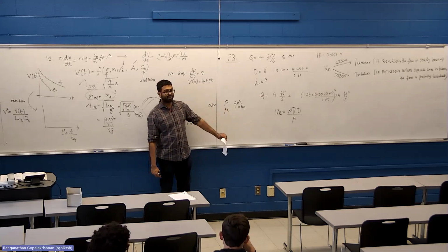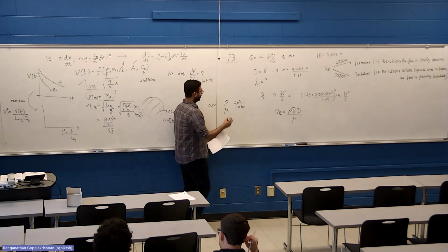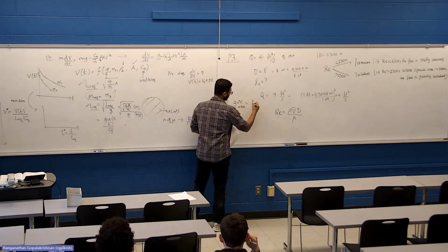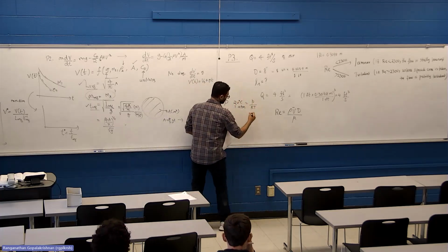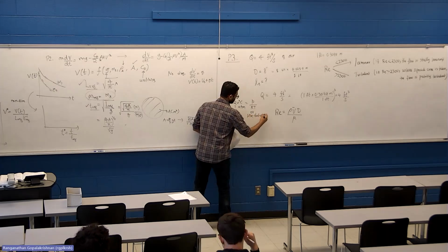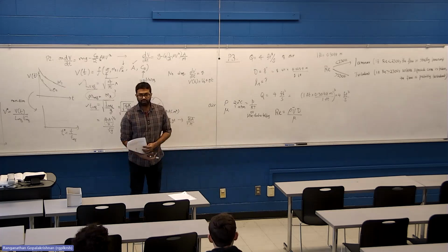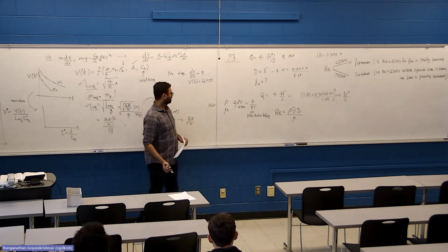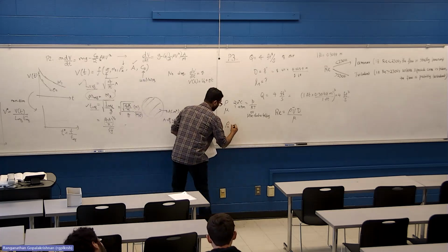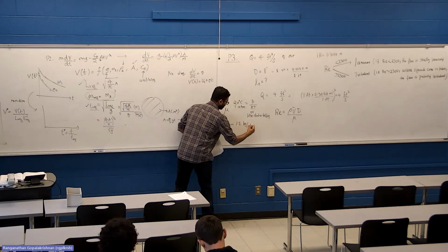Pick the temperature and pressure that's nominal and calculate density for that. Or you can do this by ideal gas equation or use data tables, which will be given to you. Look up the data table. So density of air at this condition is approximately 1.2 kg per meter cube.